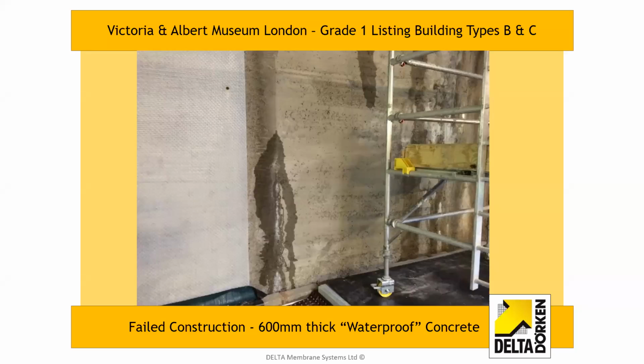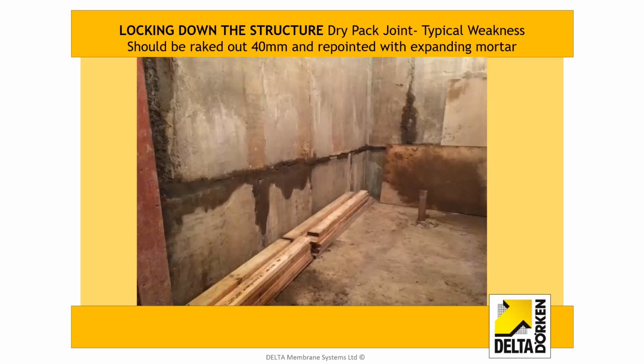Type B and Type C. The Type B concrete, the waterproof concrete, is there. Is it watertight? Well, not really, because you can see the leaks and you can see the aggregate that's exposed because it's not been compacted properly, so less than adequate workmanship. What do we do with this? Well, the first waterproofing system has partially failed, so we fix the defects in it. We stop the seepage using injection techniques or slurries and whatever. And then we've got a Type C system, which you can see the membrane coming in from the left. So managing the scope for defects during construction with combined systems.